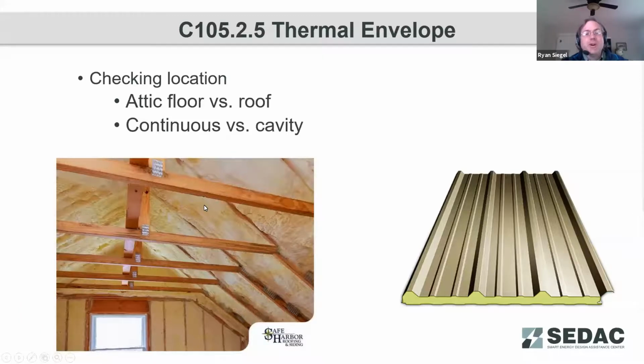Also going to be checking as far as where is the insulation located. Is it located on the floor, or is it part of the roofing assembly? Is it continuous versus cavity insulation? Here on the left, we're just depicting some sprayed in cavity insulation. In commercial buildings, it's not uncommon for insulation to be completely above the roof deck, either on a low slope roof or even on some pitched roofs, to see continuous insulation above the roof deck.